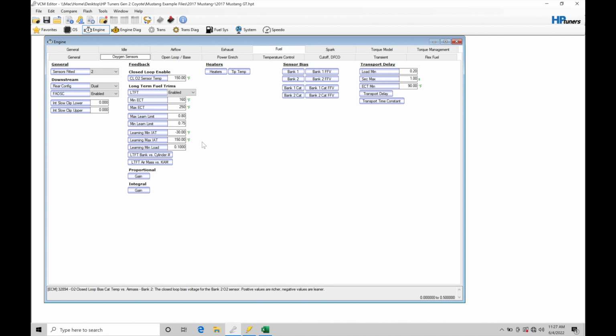So if we're finding that our oxygen sensors are reporting that we have a lot more oxygen in the exhaust stream, that means we're running at a leaner mixture. Well, if we're trying to run at, let's say, 1.0 lambda or 14.7, and we're measuring something like 16:1 air-fuel, or the equivalent of something like 1.1, 1.15 lambda, that means that we're leaner than the target.